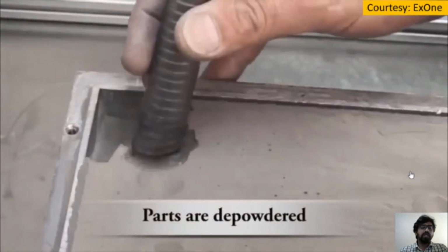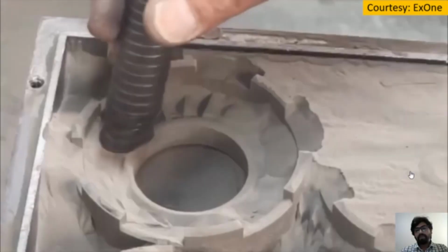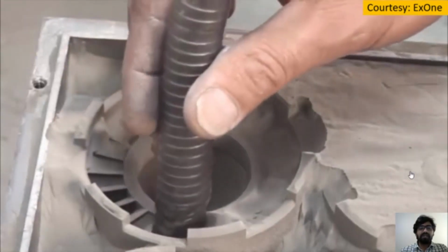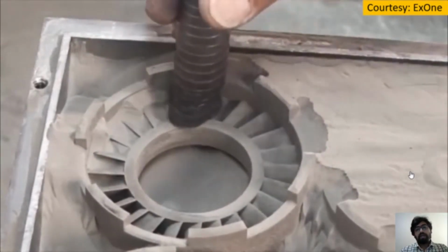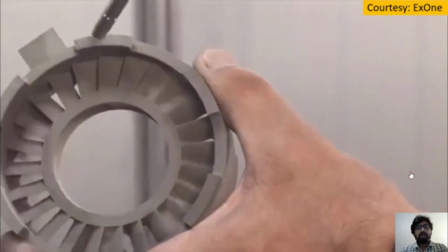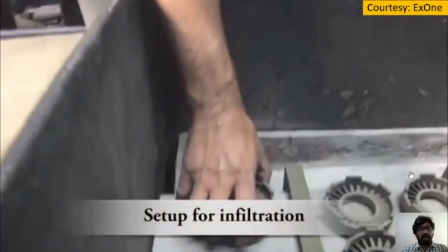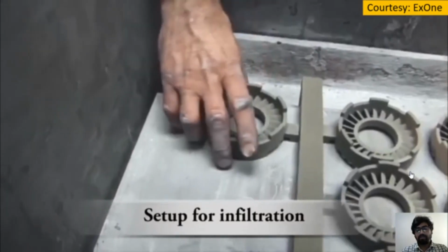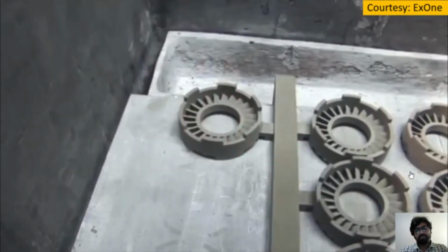Later on, the loose metal powder is collected by a vacuum pump, and the green part of the metal, in which the metal particles are held together due to the binder, will be produced. We have to take some care while handling these parts, as they are in the green state and they do not have a very good strength right now.